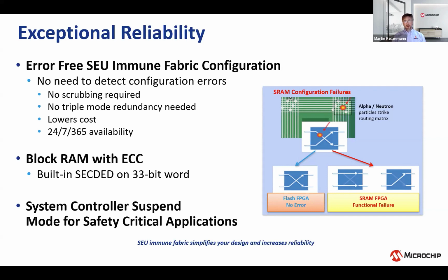Also, thanks to that configuration inside of the FPGA, you don't have this long boot up time, this power on reset, the inrush current, but the devices are typically more or less instant on and then working on low power. Also, effects like the single event upsets, which are happening on SRAM-based FPGAs, cannot happen here based on the architecture and based on the technology.